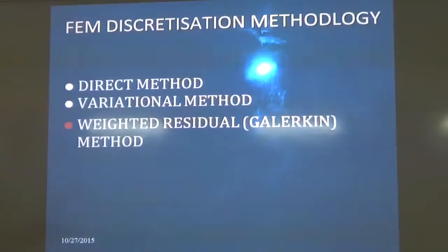For finite element, as we know, we can apply three methods: the direct method, the variational method, and the weighted residual method. The direct method is applicable mainly for simple geometries. If the geometry is very complex, then you cannot use the direct method. The variational method and the weighted residual method are both versatile.